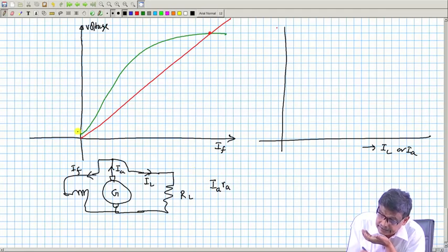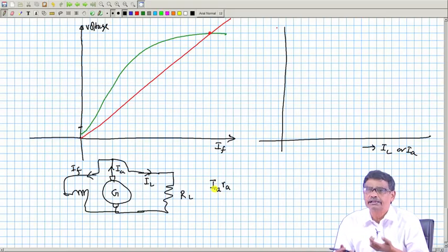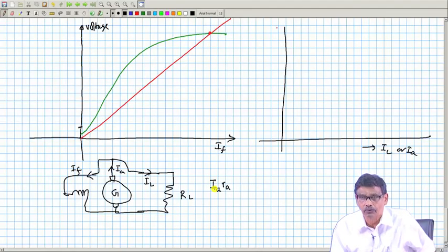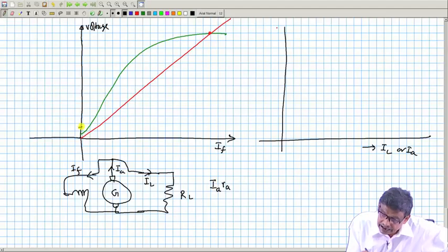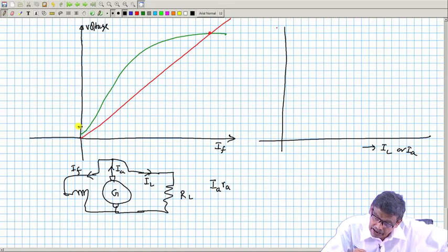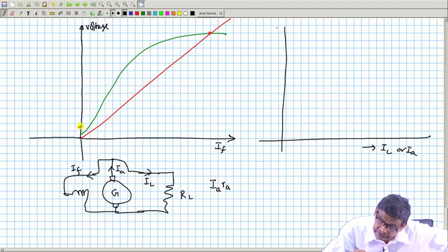And then this part is most interesting. You cut a length which is equal to this IA RA. I have assumed armature is loaded to deliver 5 ampere current, 5 into RA I know. So, 5 into RA I will calculate, it will give me some volts. That voltage I will cut as a length from this, and then I will draw a line parallel to this field resistance line like this.